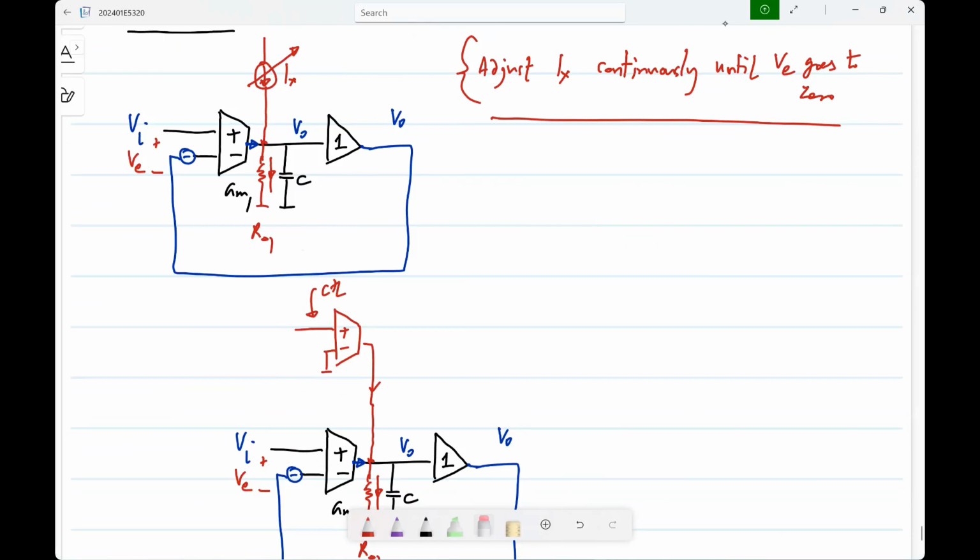Op-amp. Okay. Op-amp meaning what? What is the function? What will you do with the error? If you want this continuous change, what should you do to the error? Integrate. So basically, you have to take this VE and integrate it. This control voltage should be the integral of VE. So how do I do that? Like I said, an op-amp, and of course, what an op-amp is we know at this point.